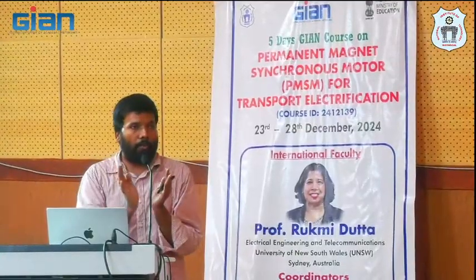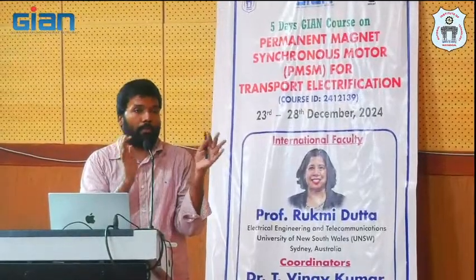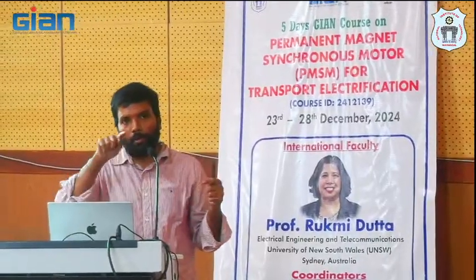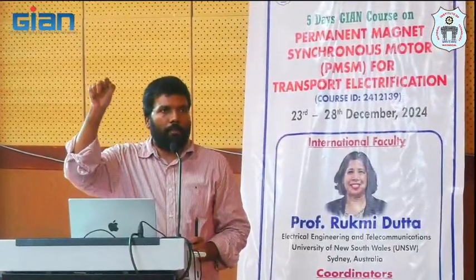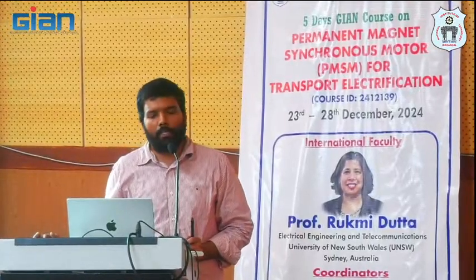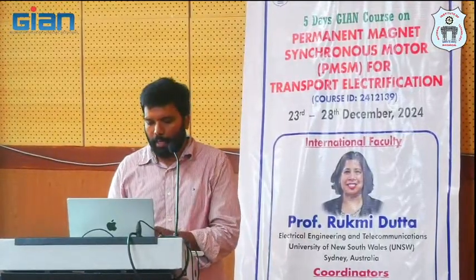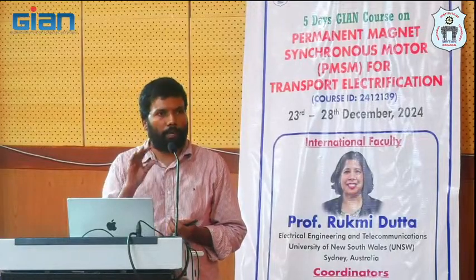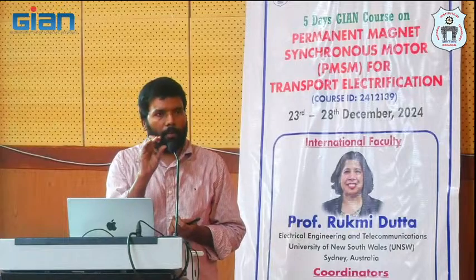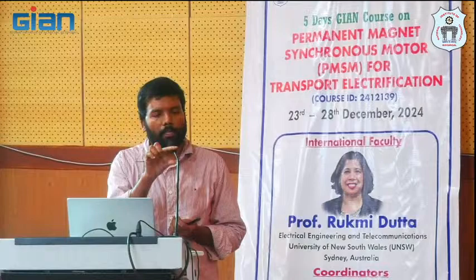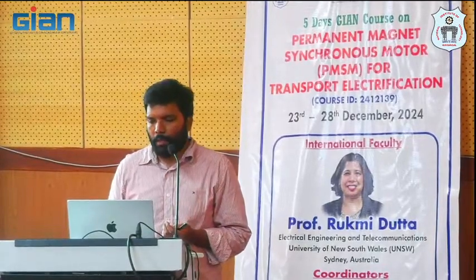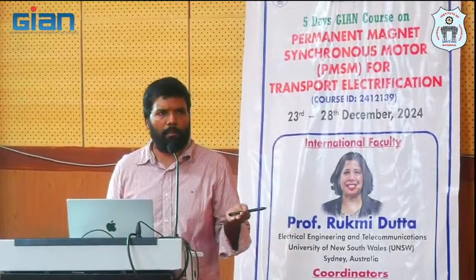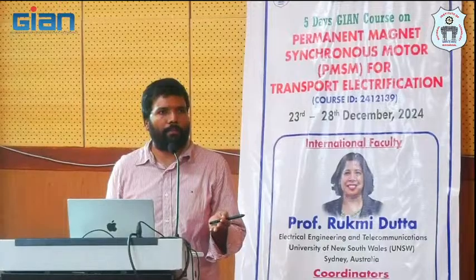You need to write the code irrespective of your reference. Your reference should not go in a step way; it has to go in a cumulative fashion. The advantage is that we can limit the current. How can we limit the current? Initially, if you take any drive, operating speed is 0. Because of your control logic, reference speed is 100, back EMF is 0, and because of impedance we can control the current.